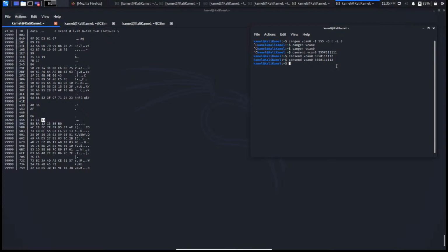There are a lot of these discrete, real-world things that are mapped to CAN data. And finding out what real-world things are connected to what arbitration ID, which byte inside that arbitration ID, that is the CAN bus reverse engineering process. That's how, if you're working on an unknown vehicle type, you learn what the different bytes on the bus mean. Which, okay, this arbitration ID is related to steering, this arbitration ID is related to braking, this arbitration ID is related to speed, so on and so forth. Eventually, you can build a full profile of this vehicle's CAN bus and use that to, well, there are a lot of cool things you can do with it.